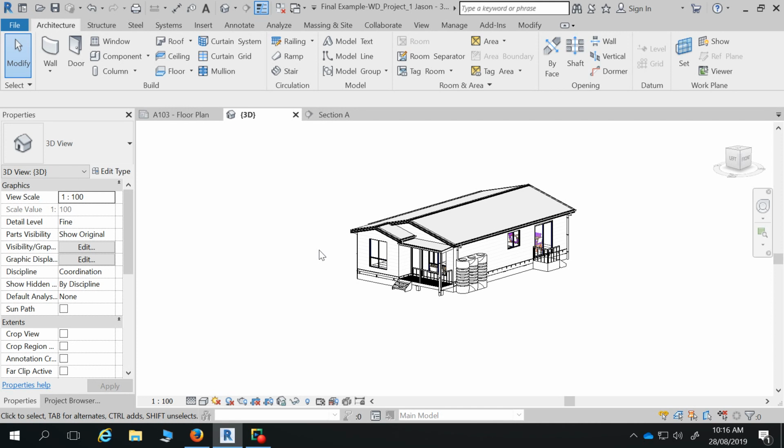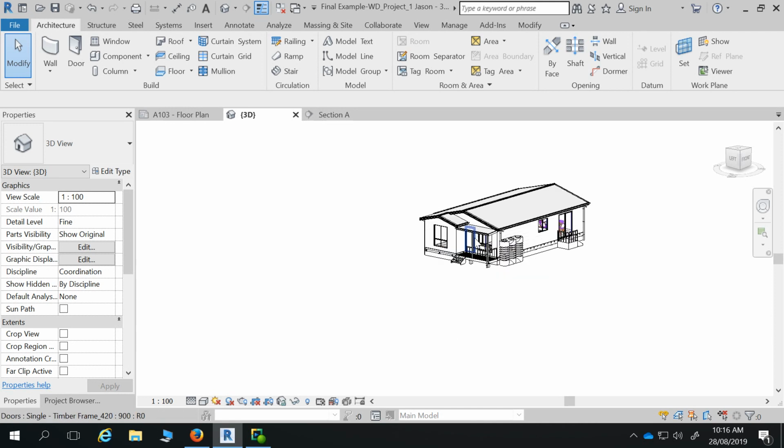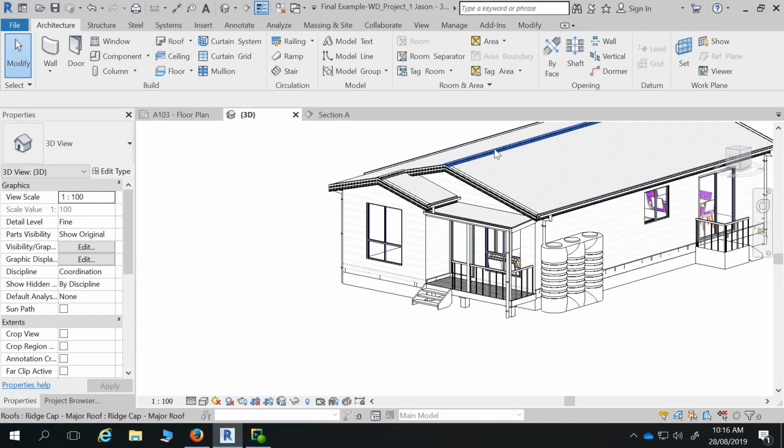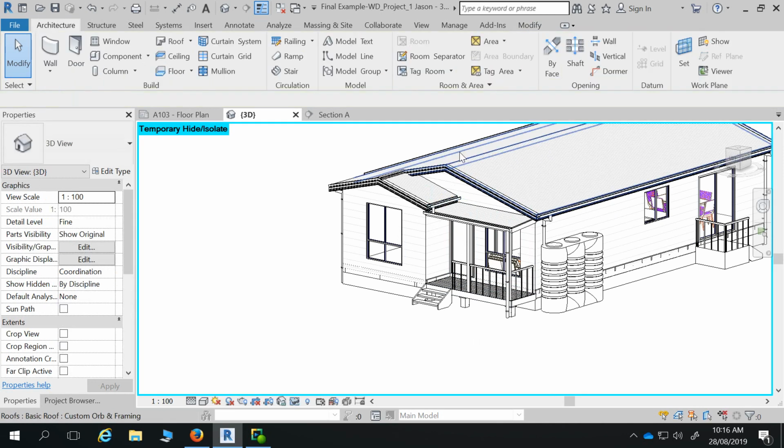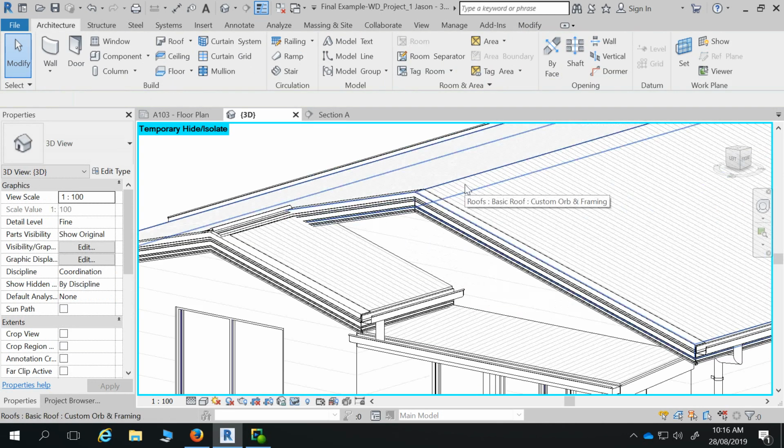So if you've got a hip and valley sort of roof as well, obviously you have the ridge capping being a bit bigger like we're doing now, but then you've got just a smaller profile capping as well. So you can draw that as well and put it as a different capping. And that just gives it the effect that it's got that capping, rather than these normal roofs that just have that straight line on them.